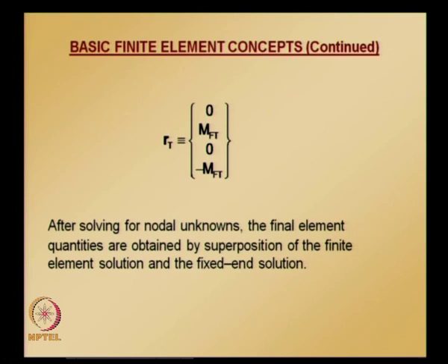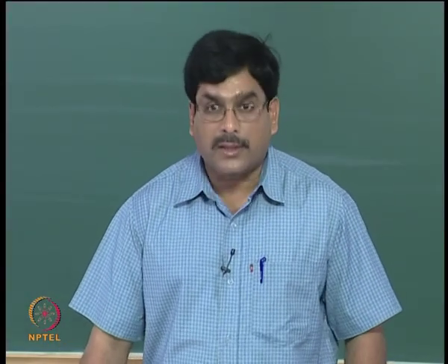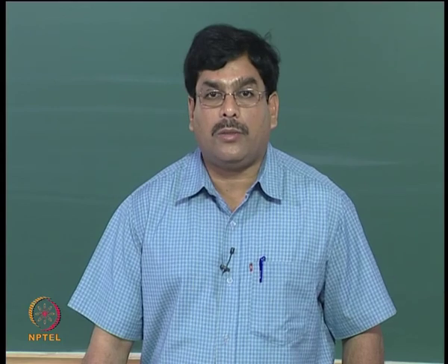So after solving the nodal unknowns, that is, once you solve the nodal unknowns V1, theta 1, V2, theta 2 for the beam element, the finite element quantities like displacement, bending moment and shear at any point in the beam are obtained by superposition of the fixed end solution, as for the distributed load problem.